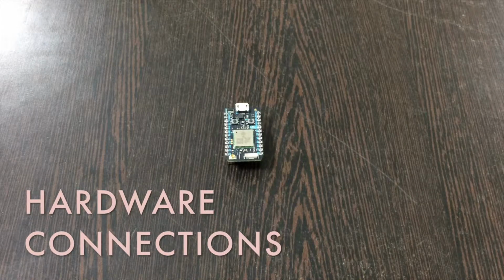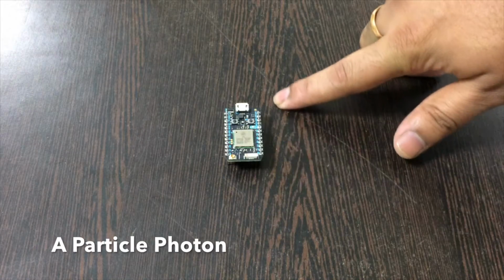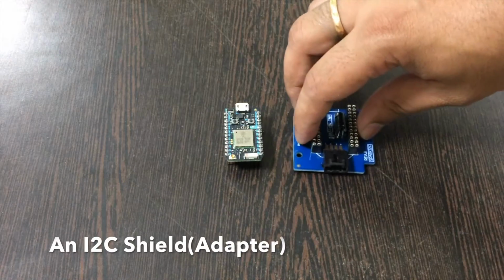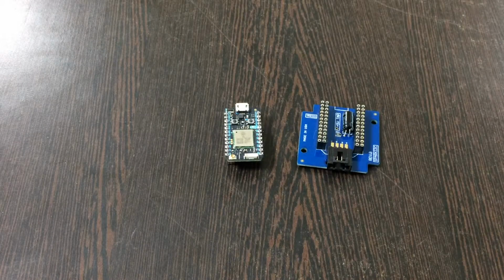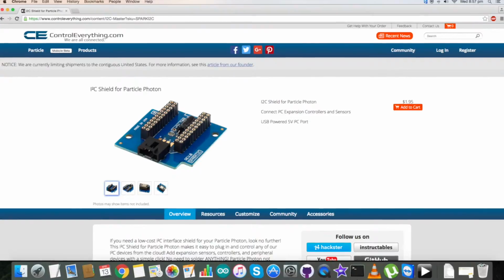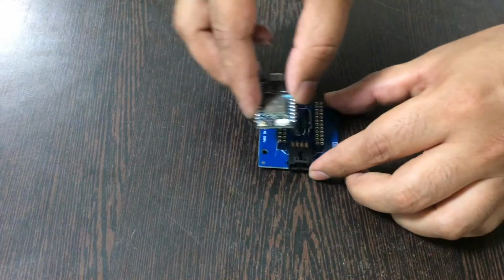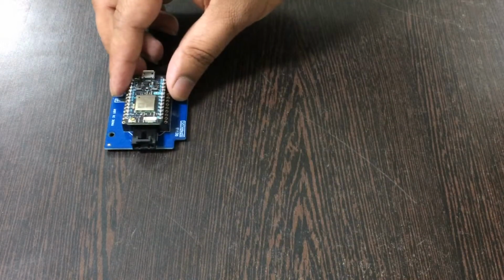Coming to the hardware section, first of all we require a Particle Photon, just like this, which you are able to see on my screen. Now this is an I2C shield. It is very useful in making connections with other I2C devices very easy, and this is available on our website controleverything.com. Now gently place the Particle Photon over the I2C shield like this and the connection is ready.